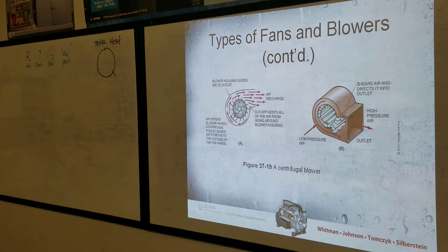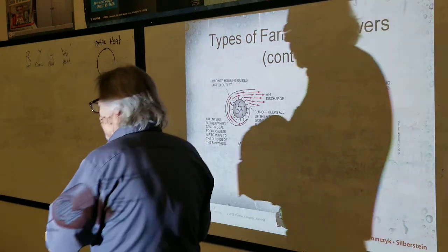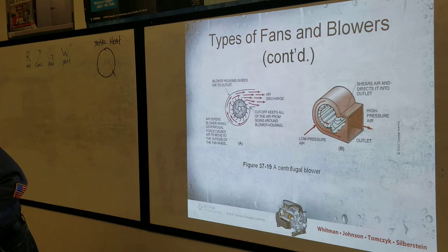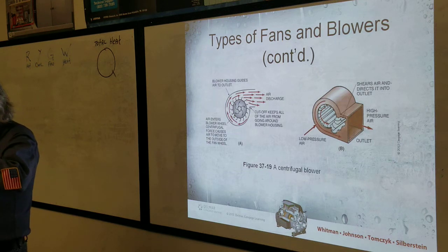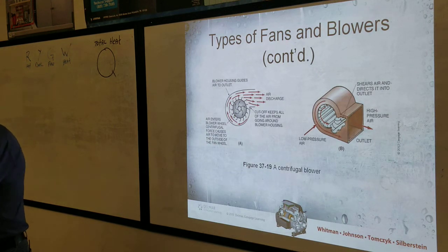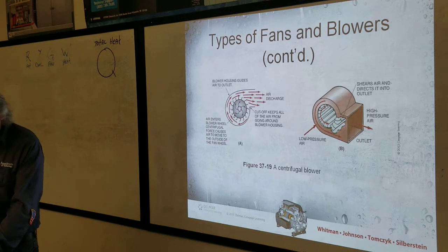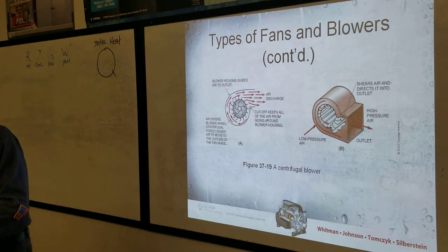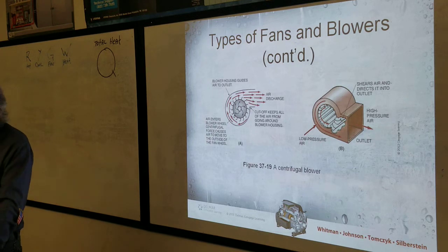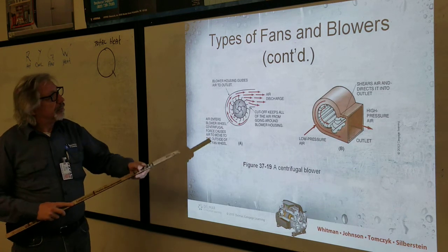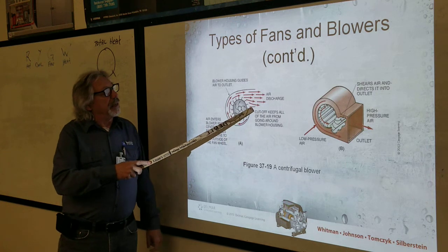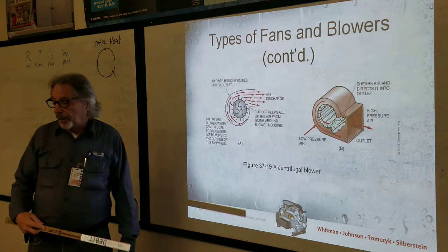Okay, there are water coolers. Here's a small one. As you can see, inside it's got a squirrel cage, motor on the outside here. This part right here, what they're talking about is the shear cutoff. It's this point right here where it actually cuts off the air. If you didn't have that, that air would kind of just keep circulating around that wheel.